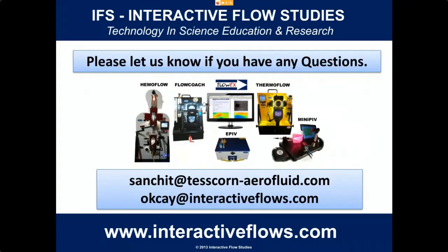With LED, what we do is we utilize the laser sheet, the camera focal plane thickness, as the plane of measurement. And our software takes care of the background or foreground noise, if there is any. And the results are pretty good. So it is not a volumetric flow. You need, I think, 3 cameras and very, very fast pulse rates for that.